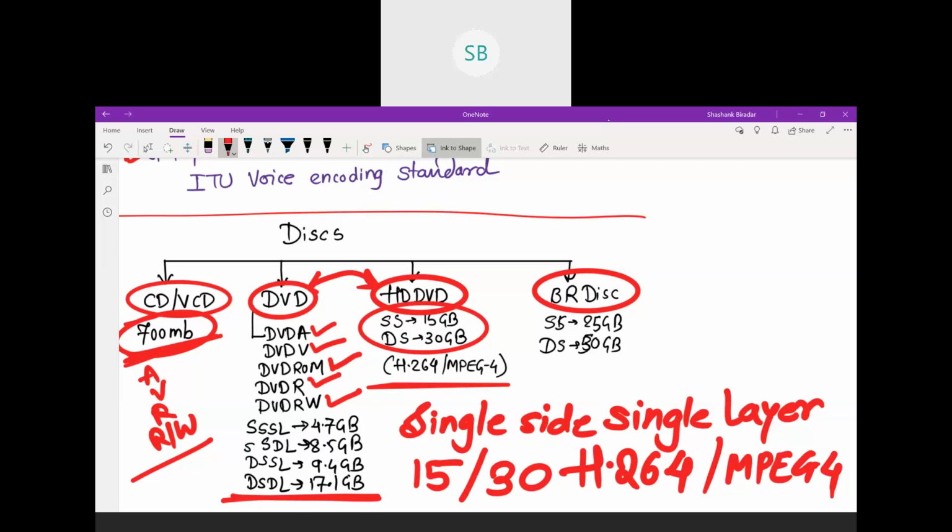So this H.263 and H.264 we have seen at the time of second unit. Am I right? The basic video compression techniques are based on the same platform in which we are compressing images by means of JPEG. First of all, let us take the image, divide that image into 8 by 8 blocks. Then with reference to the quantization table, we are performing the discrete cosine transformation. Then after transformation we have quantization, and finally encoding. Basically we are using Huffman encoding for that, and finally we are compressing the data.